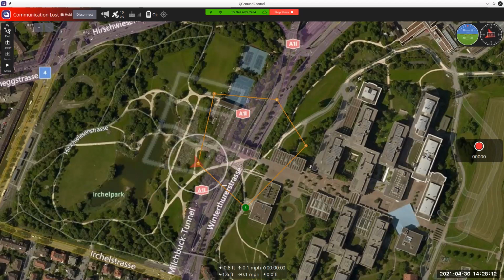You can get an idea of potential latency between them. You can get an idea of stability. I think you can make a rudimentary guidance stabilization plot. So you can see angles and angular velocity, and see if your state space is working correctly relative to a GNC solution that goes into it.